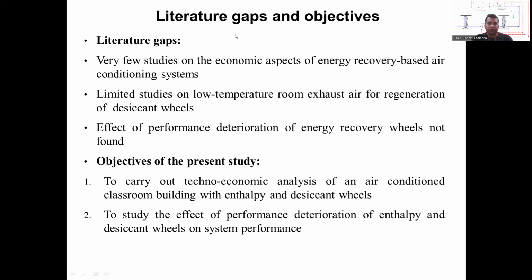Based on the literature review, there are some literature gaps, and based on that the objectives were decided. These energy recovery wheels, like enthalpy and desiccant wheels, are coated with an adsorbent like silica gel. So when high humid air passes through these wheels, there is interaction of moisture between the supply air and exhaust air. But after some time, these wheels get saturated, so we are required to regenerate these wheels for their continuous operation. For regeneration of wheels, we require some external source.